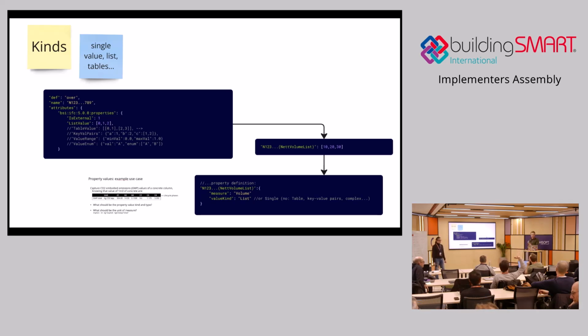Right. Thomas? Yes. Also keep in mind that the IFC table property is specifically a lookup table, so it's a table with at most 2 rows or 2 columns, depending on how you do it. There is also the reference property to an IFC table, but I think that is not being used. My point is that kind of lookup table could also be 2 separate list properties.